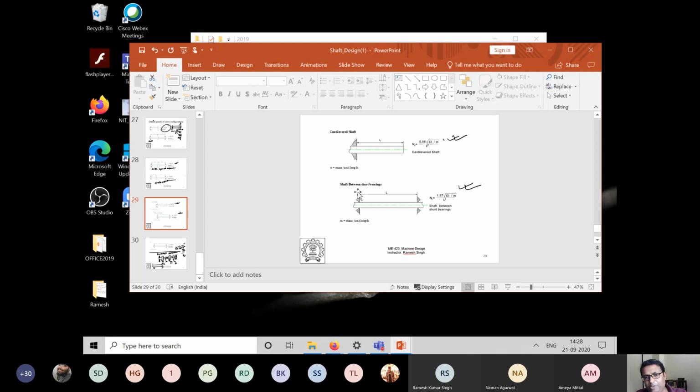If you do it, you will get the natural frequency of the system, because now the system will behave as a composite thing, right? It can have multiple impellers. Pumps can have multiple impellers, or your shaft can have multiple pulleys or multiple gears mounted on the shaft, right? So in that case, you will have to have a composite natural frequency. How do we estimate that composite natural frequency is what Dunkerley's method says. That's what I wanted to give you. So you basically assume that these are all individual cases, find out for each case, and then take the inverse of squares and sum it up.